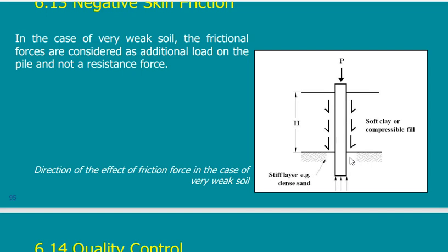But what is the load carried by the soil? The negative load of the soil alone, it is 60 tons. So the pile will fail under own weight. It was supposed to carry 100. This 100, 60 here and 40 here. Later, when this consolidates, this 60 will be added to the 100. So I will have a load of 100 plus 60. So it is 160 carried by 40 tons. Fully settled. It's a complete failure. So this is a big problem.